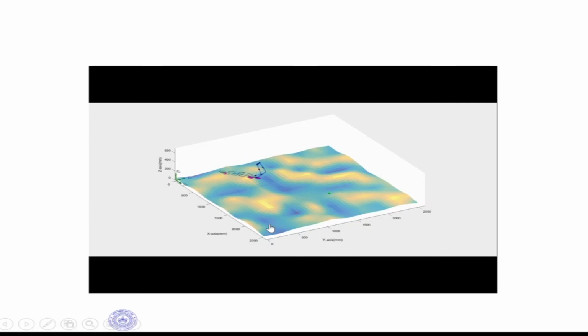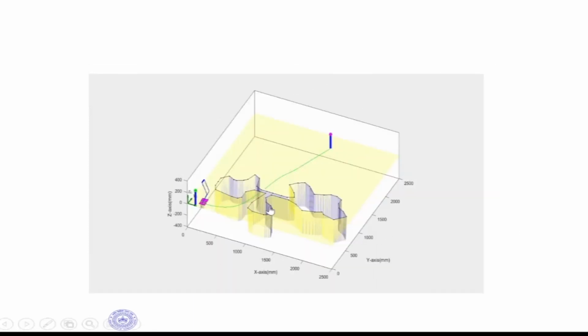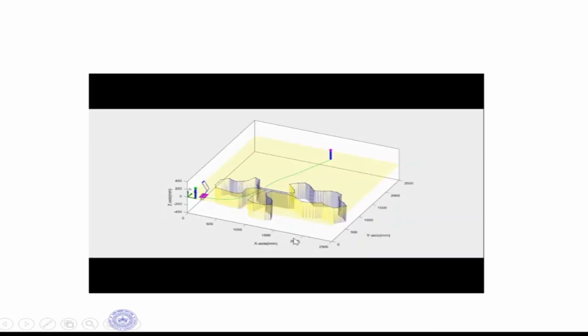It is exactly the same as the wavefront planner that we studied. So the waves try to keep to a flat ground, they don't try to climb gradients. So this is a case of a biped robot walking on 3D terrain. Now you can have a biped robot, and suppose this place is a ditch. So it should not go inside the ditch. The ditch manifests itself by a very high gradient. So the robot avoids that high gradient and tries to find a location where it can cross, by using the wavefront planner, and then crosses at that point and goes on the other side.